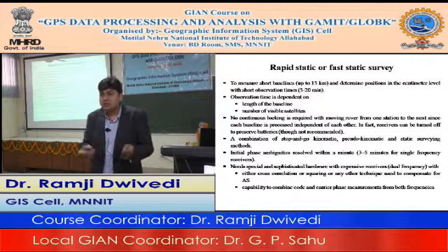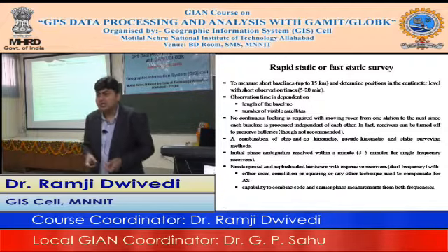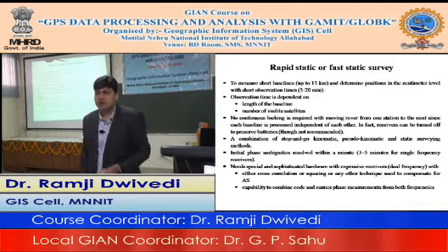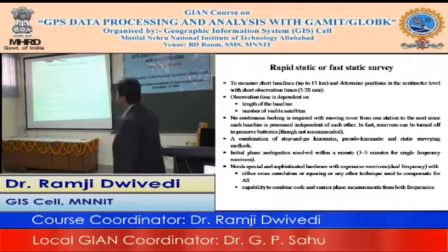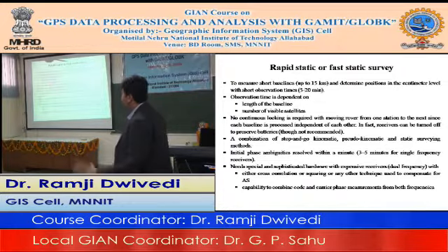because they are also using data combinations, preparing wide lane and narrow lane combinations, so that the observables get prepared well in time. They measure short baselines up to 15 kilometers and determine position at the centimeter level with a short observation time of 5 to 20 minutes. Observation time depends on two major factors: how favorable the satellite geometry is, which we call PDOP.